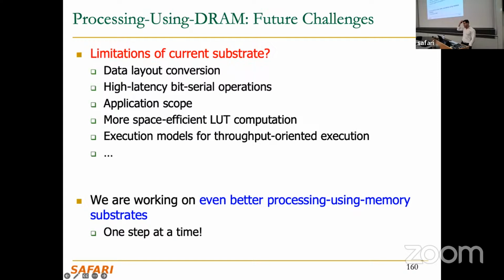Okay, so what is there to be done in processing using DRAM? I'm sorry, I have another question. The effect of the interconnect modifications, are there results that characterize it? All of this is based on another prior work called Figaro, which is also from SAFARI, and it uses something similar to move columns across different DRAM banks. There we did some SPICE simulations to see the latency of moving things, basically asserting that column multiplexer, and it's the same column multiplexer. So we didn't redo it because it would give the same results, but we reference and point to that paper.